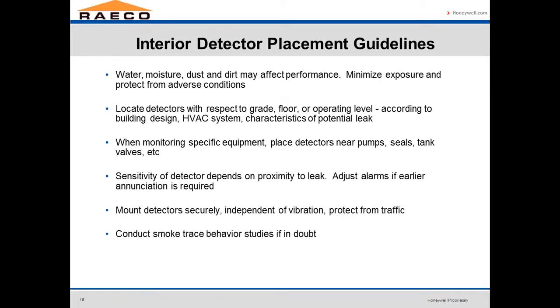Again, we'll talk a little bit more about detector placement. You want to make sure that you keep these things away from water, moisture, dust. Try to minimize exposures to these elements. Locating detectors with respect to grade, we talked about gases that rise and fall. You need to determine where to place those. Monitoring equipment, again, near pumps, valves, seals, that's always a good idea. Sensitivity of your detectors, again, depends upon how close you get these things to potential leak sources. So you want to be aware of that.